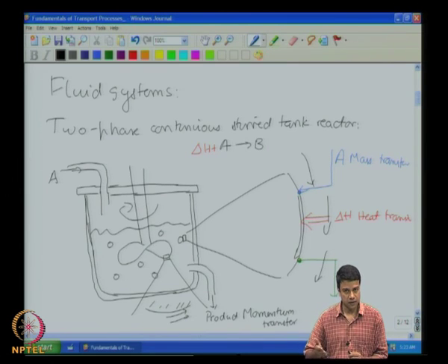It is important that reactant comes in continuously so that the reaction can take place, and it is also important that the product leaves the surface, because if the product does not leave, there will be no place for further reactant to come in. In addition, the reaction can be either exothermic or endothermic, so you have to supply the requisite amount of heat or remove the requisite amount of heat from the surface. Otherwise, if it is an exothermic reaction and you do not remove heat, there are going to be hot spots that are formed and you could have runaway reactions. If it is endothermic, then if heat is absorbed, the catalyst surface will cool down and the reaction would not proceed at the desired rate.